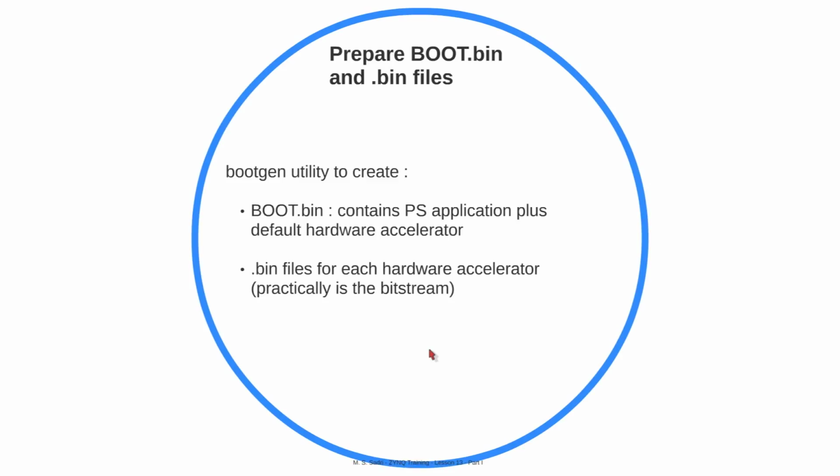For the .bit files, you use the bootgen to create the .bin file, and actually the process is exactly the same as the process that you use to create the boot.bin file, which you put on the SD card in normal use cases, where you have the FSBL and you have a user application and you have a bitstream and you want to program your ZYNQ device with that set.